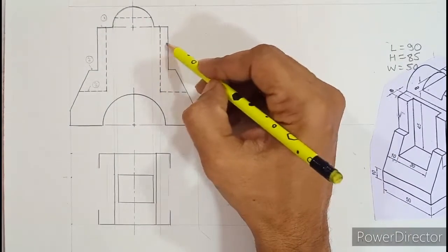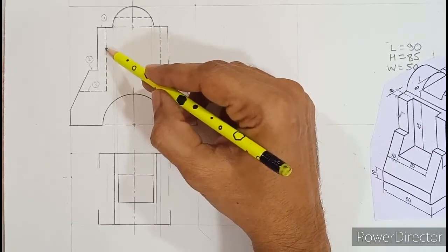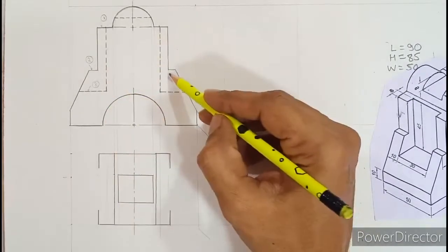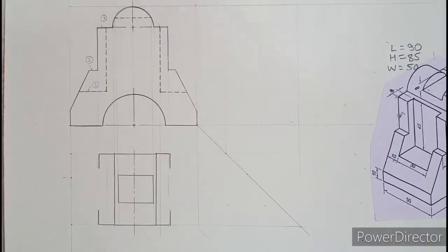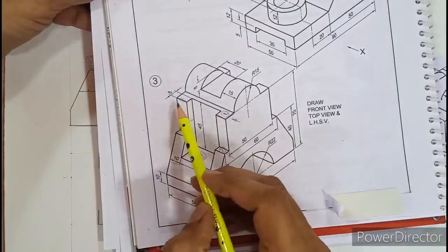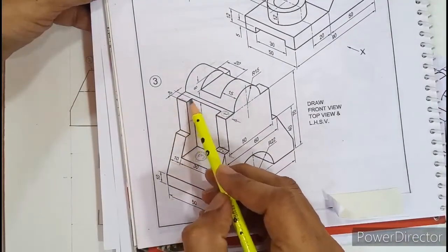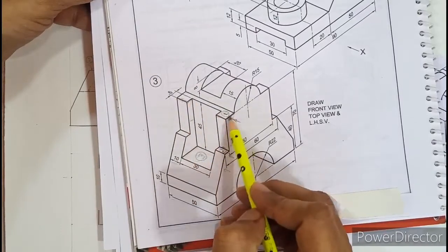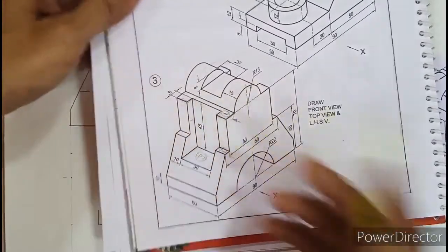So this 6 millimeter that you drew in the front view, we have now projected it down. Okay, and we need to resemble the question, which says that after marking 10 you have to move in by 6 and close this C type on both the sides.